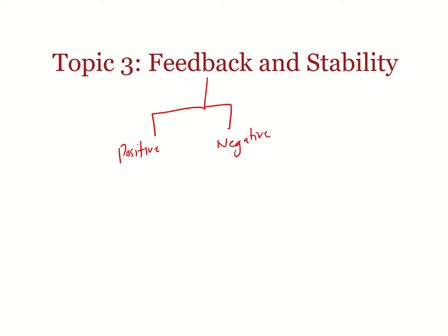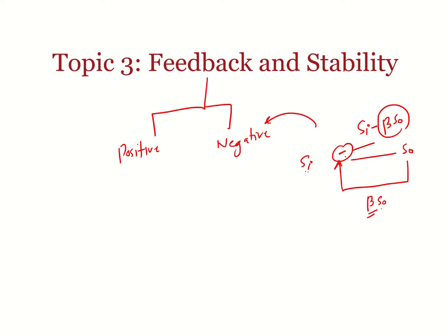In negative feedback, basically what is happening is that a portion of the output signal is subtracted from the input. Like you have input, you are getting some output, so a portion of the output signal will be subtracted from the input. For example, let's say the output signal is multiplied by beta, and here we use a subtractor, so we get the input signal minus the portion of the output signal. This will be the negative feedback, and in positive feedback we will have a summer here, so we get the summation. That will be the positive feedback.